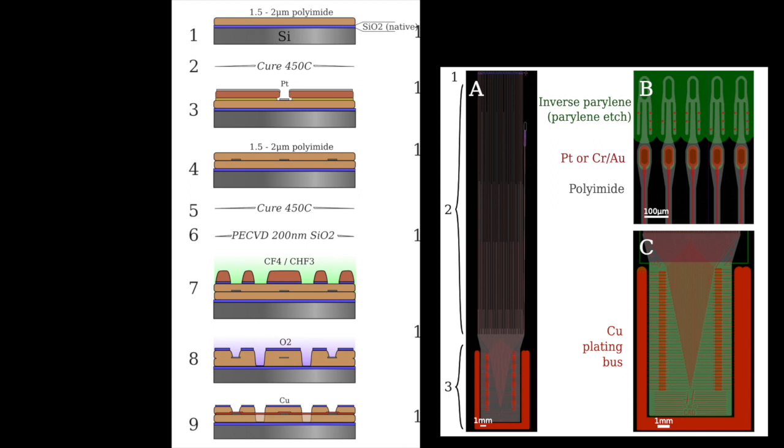So at this point, copper is evaporated onto the board, as we discussed earlier with other metals, and then etched into the correct shape, which is needed for it to function as an electrical bus. This is done by applying another mask template and then soaking it in an iron chloride solution, which dissolves any of the unmasked parts of the copper it comes in contact with. By looking at another figure in the paper, we actually see that the copper bus is not applied to the whole length of the thread. The distal ends of each thread, which go into the animal, do not get copper buses. Only the proximal portion of the thread bundles, which need to be put into electrical contact with the PCB, are covered with copper at this point.